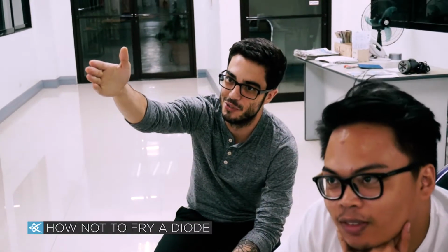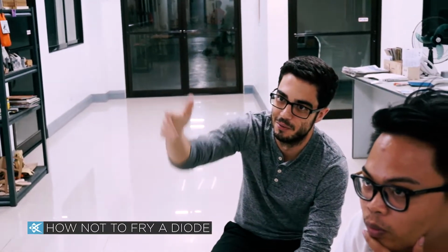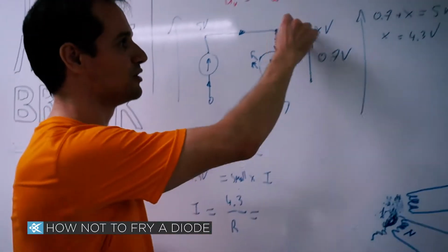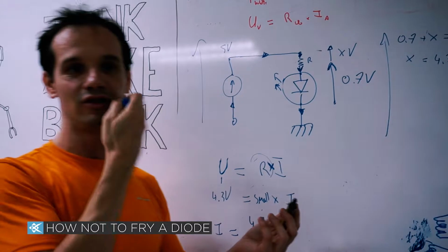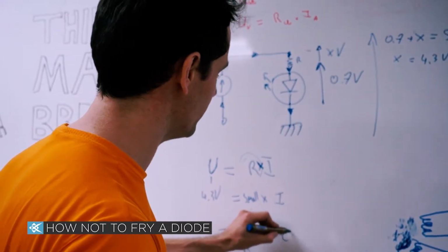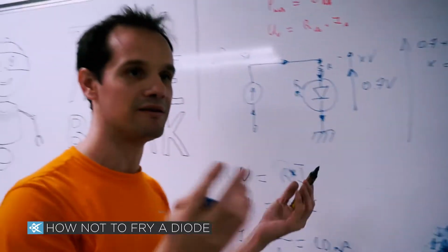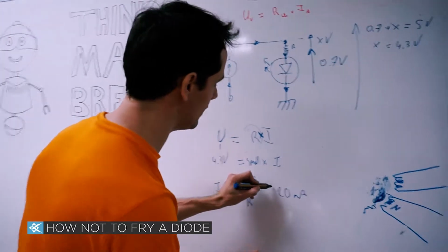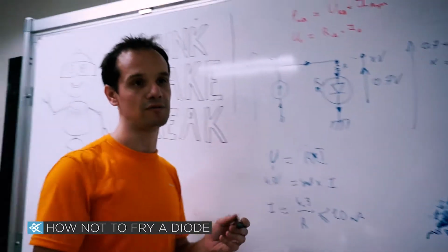So does that resistor go somewhere? Yeah, so that's exactly what we're going to do. To reduce the amount of current, you just have to find the value of R here, because you can add R to a circuit. That's very easy. It's just adding a resistor into a circuit. That's going to make I equal to about 20 milliamps, and then you'll be happy. In fact, it's not that exact, you don't really care. You just want to be less than 20 milliamps, approximately, right?